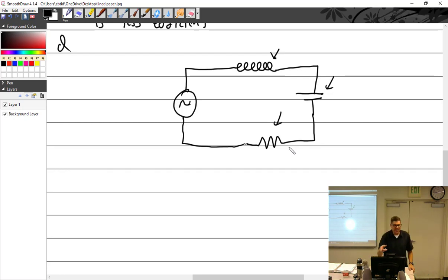In this case, the wire doesn't move, but the magnetic lines move. That's the whole key to this. When magnetic lines grow out, the magnet moved. When you take away the magnet, they move this way. Magnetic lines moving back and forth across a wire create voltage.